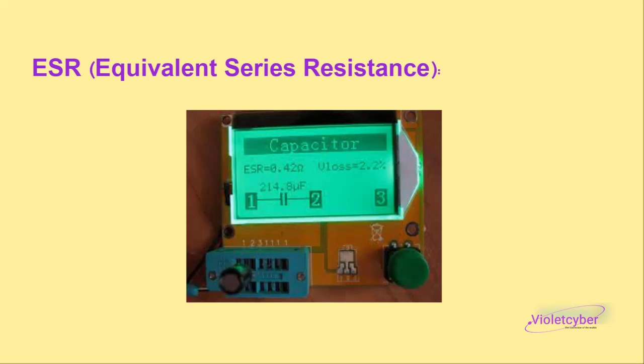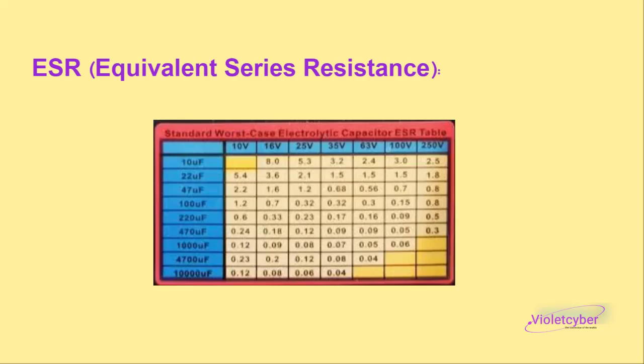Practical note: for DC to DC switching circuits and circuits requiring fast filtering, capacitors with low ESR such as ceramic capacitors should be used. Electrolytic capacitors generally have high ESR and are better suited for lower voltage filtering and low frequency applications.